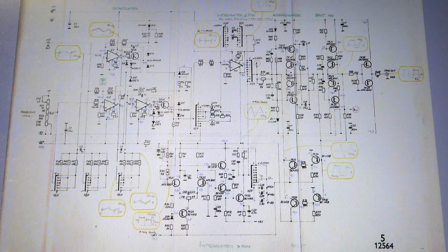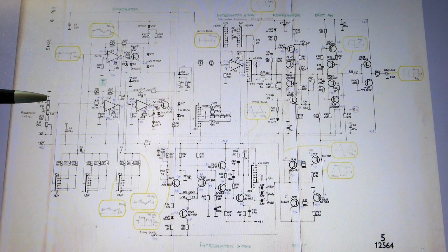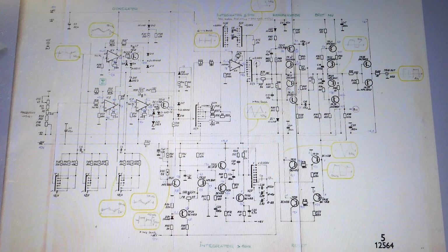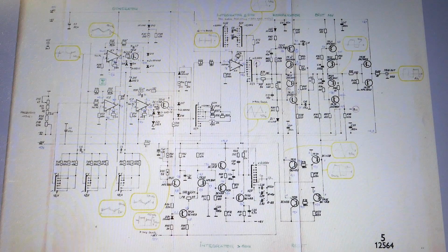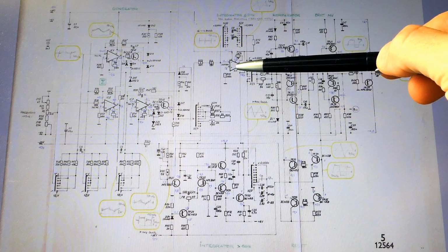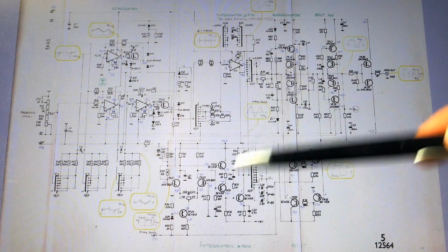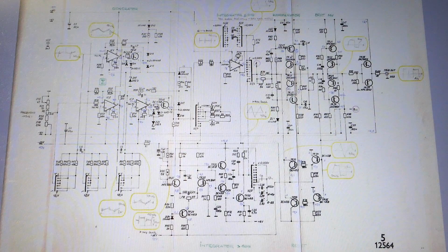And I did some frequency and duty cycle alignment. And the dial of the fine frequency potentiometer is adjusted using these trim pots. This one for the highest, this one for the lowest, but they affect a little bit the opposite, so you have to iterate several times. I also adjusted the offset null potentiometers of the 3 OpAmps for 0 offset. And then I adjusted this offset null potentiometer of this metal OpAmp in the integrator, and this offset null potentiometer of the discrete OpAmp for 50% duty cycles.